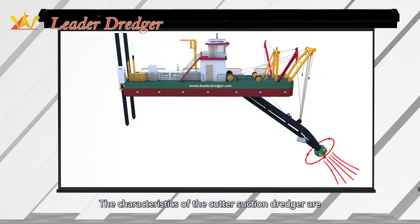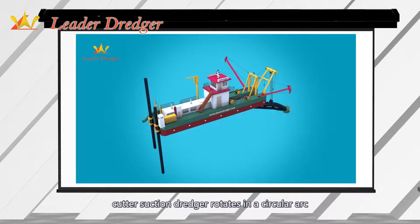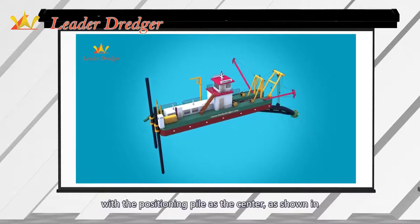The characteristics of the cutter suction dredger are: it is a static dredger, and the cutter head is installed as a digging tool to make the soil sucked after cutting. In the process of sucking mud, the cutter suction dredger rotates in a circular arc through the anchor cable fixed on the side winch with the positioning pile as the center, as shown in the figure.